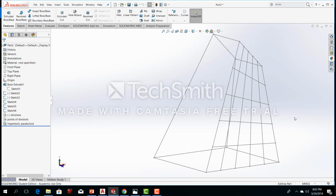And maybe we'll figure it out very simply by drawing an end view, bringing our point down and realizing, oh, that's not matching up. So what are we seeing here then? And continuing on then to explain to the students and hopefully teasing it out of them. Maybe they'll be able to tell us that that surface isn't a flat surface, that it's a hyperbolic paraboloid and it can't be developed onto a flat surface because it is a warped surface.